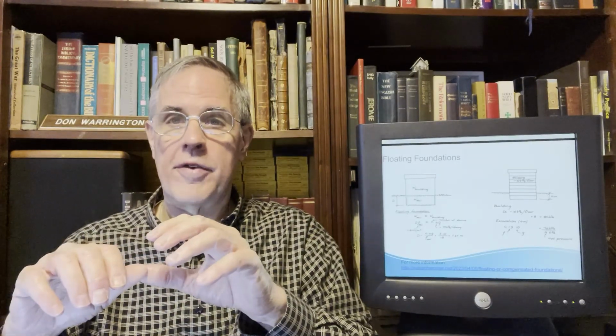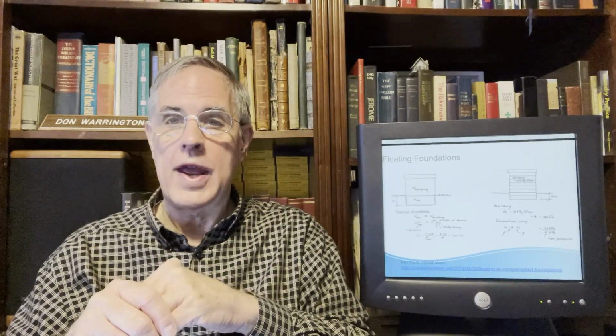And if you've got a rectangular type of plan form and straight sides, then you'll get a situation like we have here, where the volume of that displacement is equal to the length times the width times the depth, and if you have a uniform load on that, then we can essentially divide out the two lengths and the depth, and we can use a per unit area type of approach to determine how deep our ship will go. And we can do something similar with buildings, although there's a little difference in that.